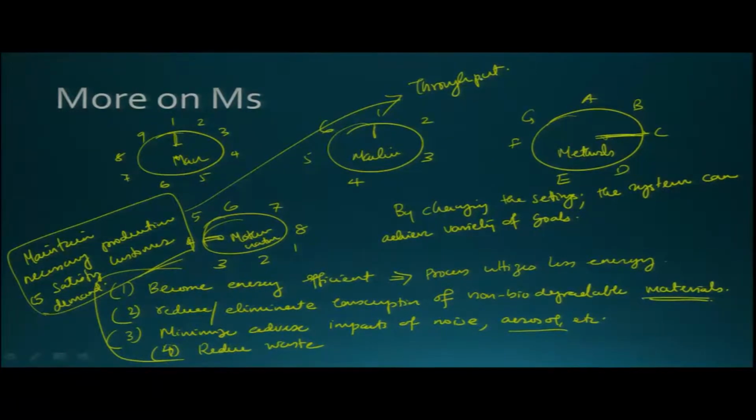So, for example, if you are making 400 units of a product and you have an 8-hour shift to make this, then 8 hours is 8 times 60, which is 480 minutes. So, if you have 480 minutes and you have to make 400 units, then we can find out how many units you need to make per minute. It says you have to make more than 1 unit a minute, about 1.2 units a minute.